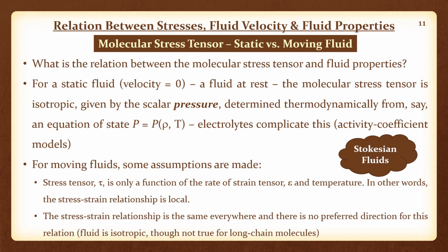Such fluids for which I can assume, one, that the stress-strain relationship is local, and two, that the fluid is isotropic, are called Stokesian fluids.